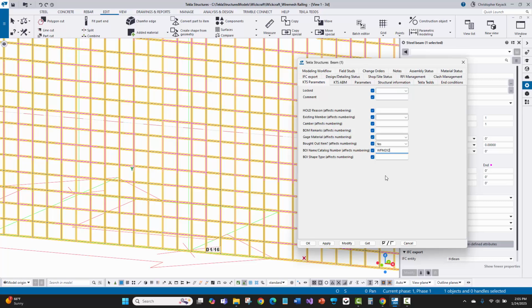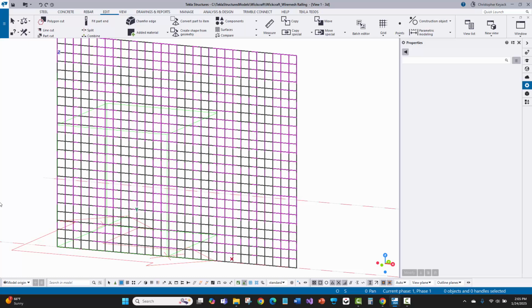Now also on the Tekla PowerFab side, if I were exporting this through the XML and the PFXT file exports for the export to Tekla PowerFab, it reads this bought out item attribute, and this is what the profile description would output.